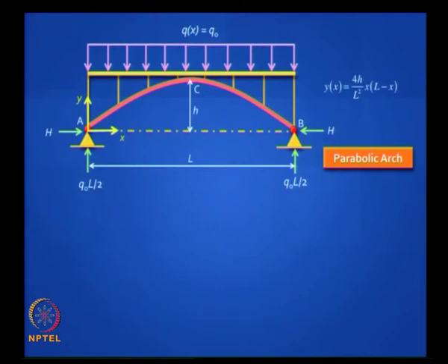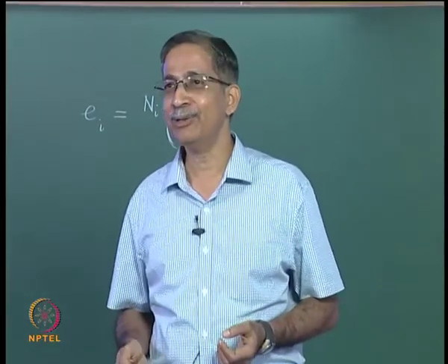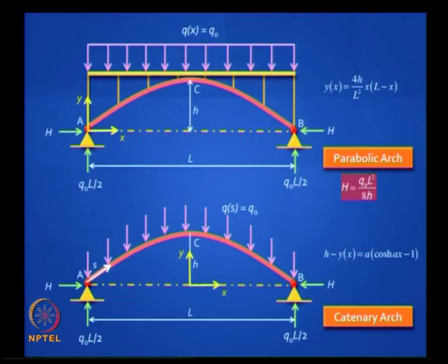This is the parabolic arch. Where do you encounter these arches? In bridges, yes, in bowstring girder bridges, but you can also encounter them in buildings, and I will show you a picture where we did this. In entrances. Now this is a two-hinged arch which is funicular. The boundary conditions are not important, so if you have a uniformly distributed load along the horizontal span, the parabola is the ideal shape.